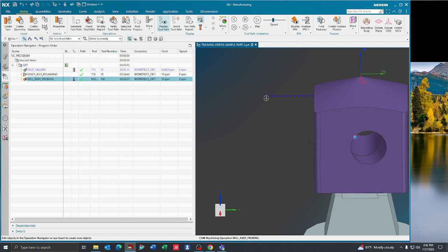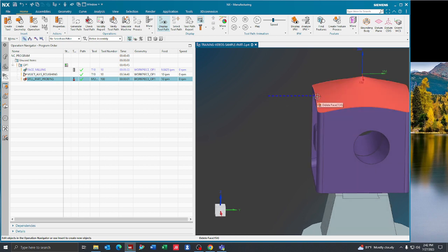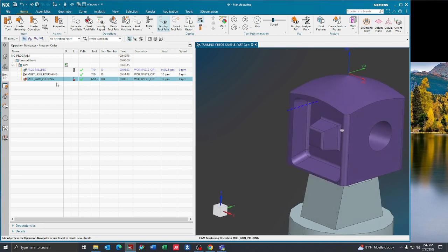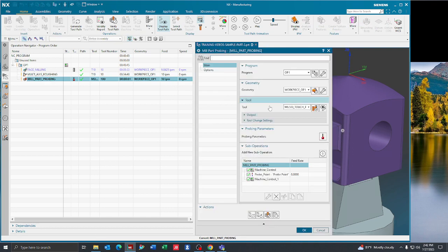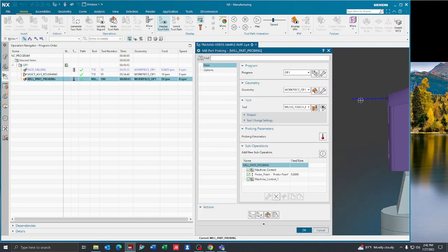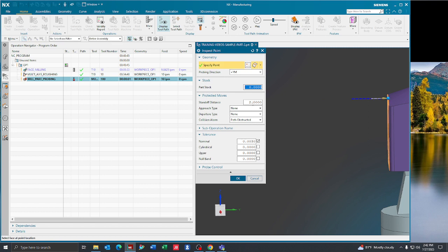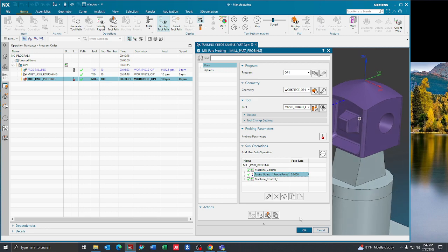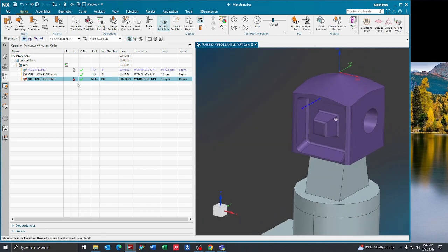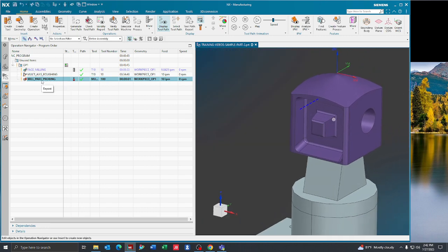You can now see that there is this blue line traversing to the toolpath, or to that point that we selected. That line is the length that it is here because of this standoff distance. You can change this to be whatever you need it to be. Some machines it might have to be within 1/2 of an inch of the point. Some it may not matter. It's just going to move until it touches that point that you're giving it. But that's just going to be totally dependent on the machine and the control that you have. But that is how you probe a point.